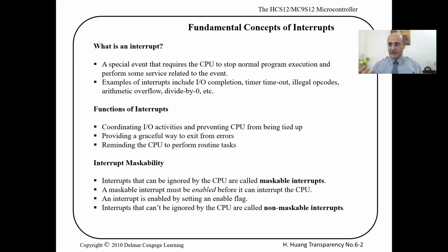Okay, so the concept of interrupts came up. What does an interrupt mean? If you want to translate it into code, it means keep your for loop empty, or with the minimum amount of tasks that you want to do. And if a button is pressed, it will trigger a hardware that will make the program counter point to somewhere, the subroutine, the interrupt service routine, do whatever you want to do when the button is pressed, then go back and keep doing your housekeeping task. So this is the main concept of what an interrupt is.